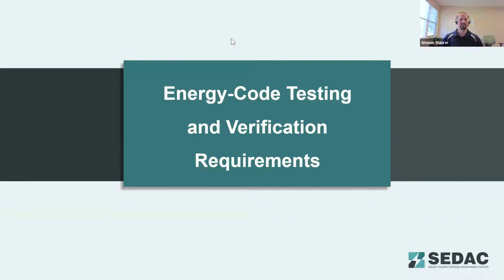And commercial and residential testing of the entire ductwork isn't required all the time either. Commercial, it's only required on sections of the ductwork that have that high pressure label on them. And again, for residential, it's only required if ductwork is outside the conditioned envelope, so it's not always required. So the correct answer there is that middle one. Those high pressure ducts need to be tested.